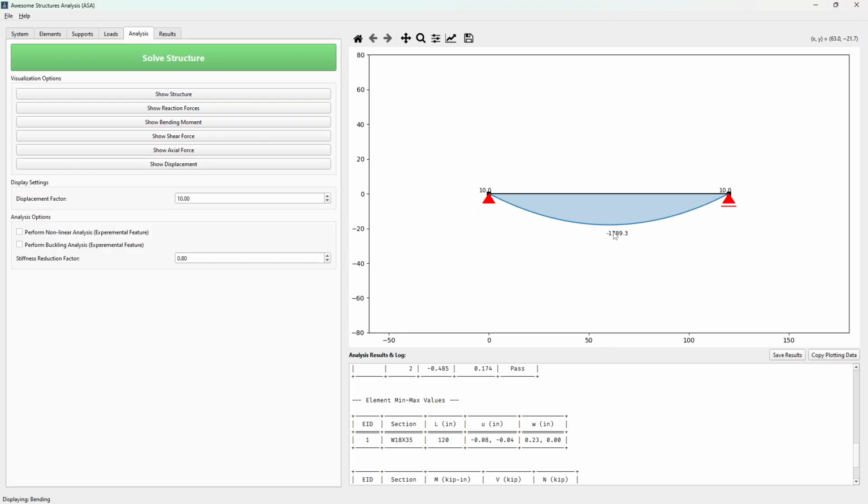This is common in other software. They don't show it to you positive. That's because you need the rebar at the bottom. Wherever the moment's pointing, you need to place the rebar. That's how other software uses it. If you study in the US, you will see the moments plotted upward, like frowning at you. Okay.